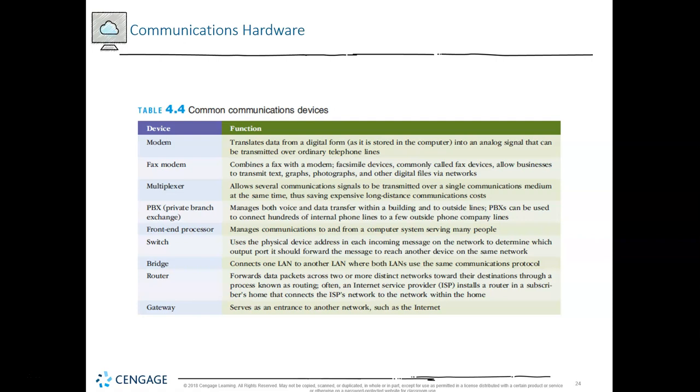So again, let's look at this briefly. Modem means modulator, demodulator. Let's see how it describes analog signals. What happens is you take your digital signals for the network signals, turn them into phone pulses, analog phone pulses, send those over the telephone network, and on the other end, another modem, modulator, demodulator, will take those analog signals, those pulses, and in that is encoded the data that can be turned back into digital. So that's the way it used to be done. It's kind of a kludge if you think about it.